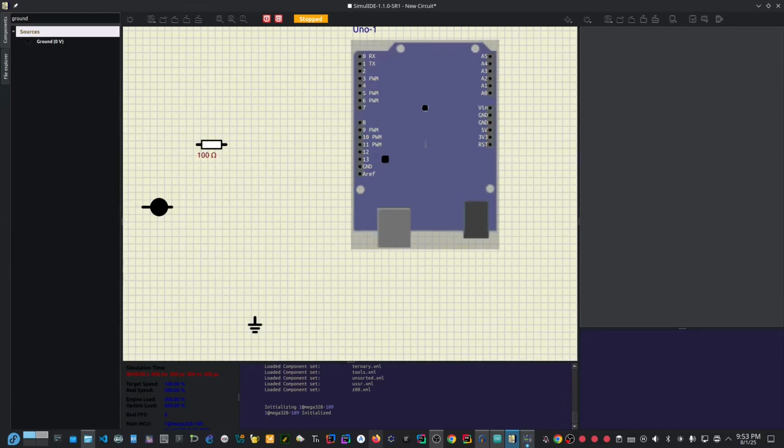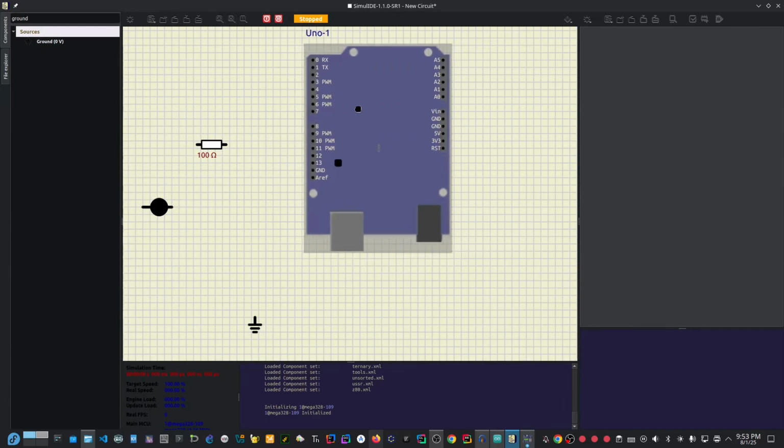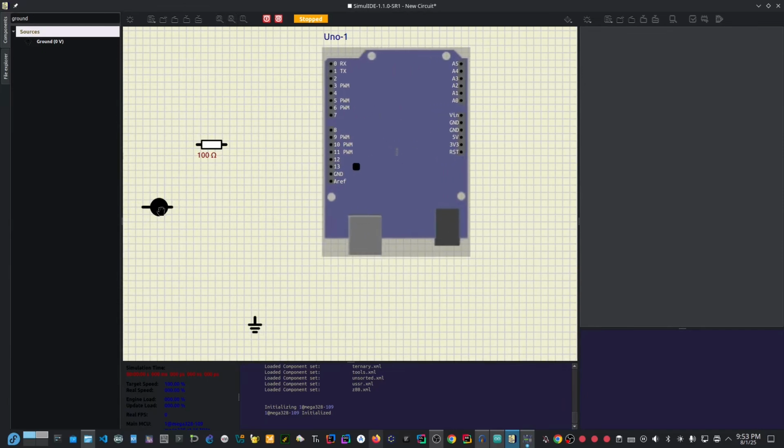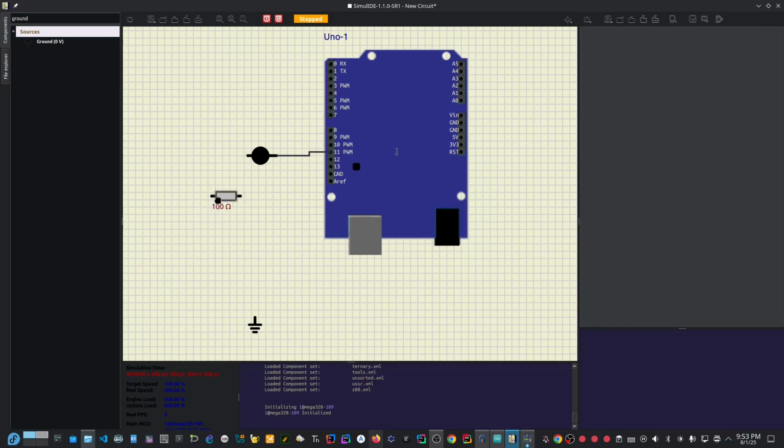Now this is the Arduino Uno here. We make use of pin 11, right? This is my LED. Let me reverse it so this is my anode side. Let's go to pin 11. This is my resistor. It is good for you to attach a resistor if you are doing it in a live mode.